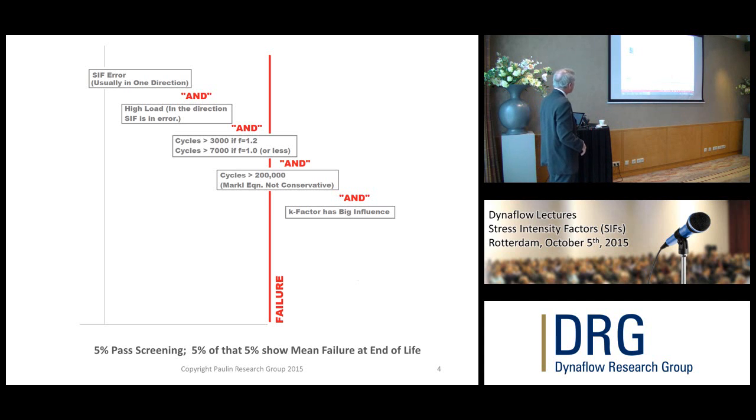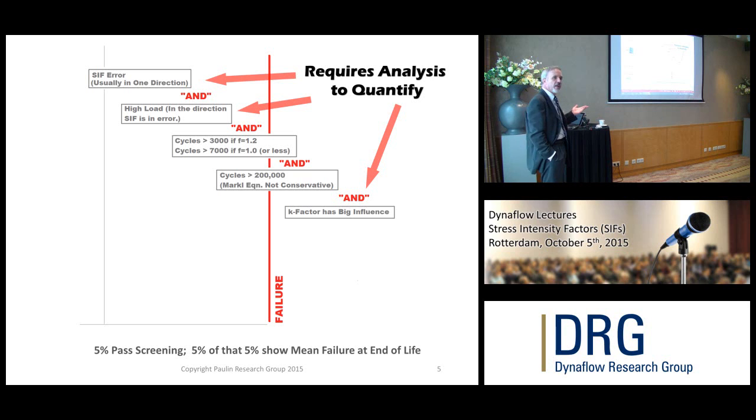Okay. So this is the trend. Some of these steps will involve analysis. So what I'm going to maintain is that if any of you do pipe stress analysis in this room, through the next 5 to 10 years, your workload will go up a bunch. And it will be the kind of workload that you can't ship to somebody who doesn't have a high degree of capacity or capability in doing pipe stress, because you're going to have to be able to decide if something's going to fail or not. You're going to have to decide how critical it is. You're going to have to decide how you want to inspect it, decide what priority you need to assign to it to inspect it, because you can't inspect everything everywhere. So somebody's got to make good engineering decisions.